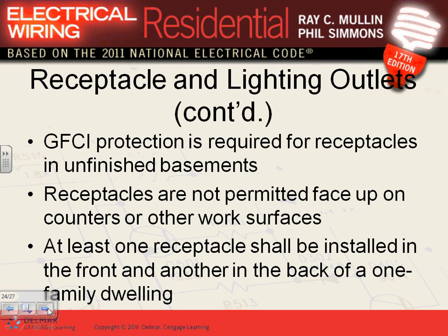I didn't talk about equipment, guys. Equipment, you always give them a dedicated circuit. We'll talk about equipment. Any dishwasher, washing machine. Washing machine is part of the laundry, but dishwasher, garbage disposal, 20 amp circuit, dishwasher, 20 amp circuit, sump pump, 20 amp circuit, exhaust fan in the common area, 20 amp circuit, and so forth.